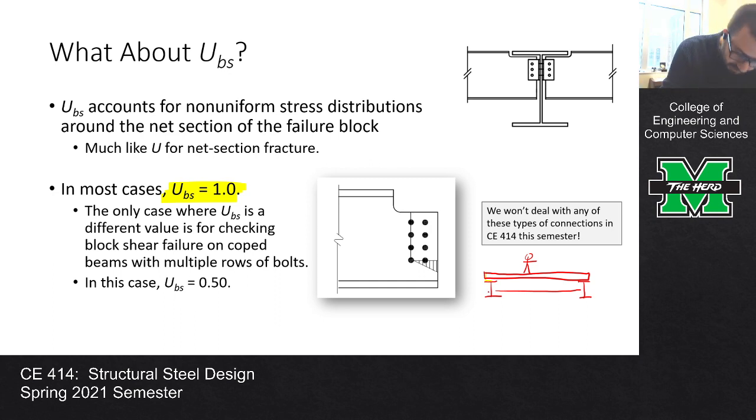So what you do is you cut a little nubbin out of the top of that floor beam on each end. So you can see where that's happened, right up here. You can see that they cut this little nubbin out, this little region right there. You cut that little nubbin out so that when you frame the floor beams together, they sit flat, okay? And so we have a name for that. We call it a coped beam.